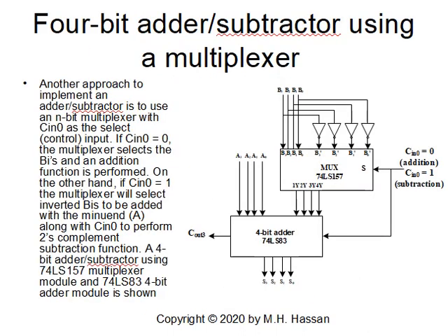Now, enough of this. If we would like to avoid the ripple, we use a chip which is not a ripple adder chip, like the 74LS83, with a multiplexer, which is the 74LS157. The concept here is very similar to the previous circuit. The multiplexer will pick up either the B's or the B nots, meaning either the B's or the complements of the B's.